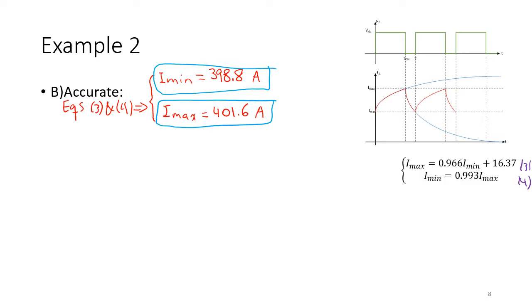can be calculated simply. As you can see, these are very close to our average value. That's why when we solved the half bridge, we said it is very reasonable to assume that current IL is equal to its average, IL bar. See, it doesn't change very much from 400 amperes, it remains very close to that value. Just to see how much is the error of what we have done if we assume IL average to be IL, let's calculate the IL average here.